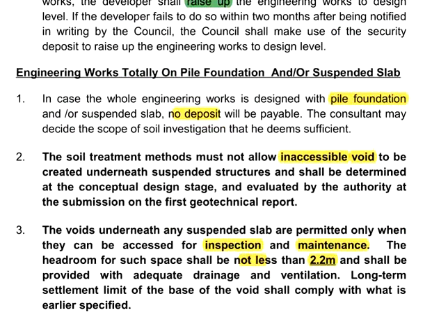Now, if the developer chooses to use the suspended slab and the pile foundations, there will be very minimum risk of excessive settlement. Therefore, no deposit shall be required. However, there are conditions. The soil treatment methods must not allow inaccessible voids to be created underneath the suspended structures, and this shall be determined at the conceptual design stage.